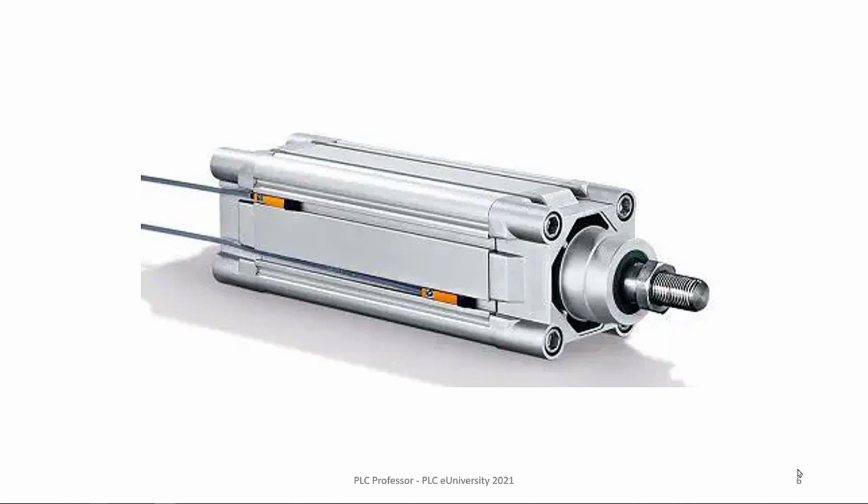Okay, so let's get back to this Hall effect. You've got electrons flowing through this conductor from left to right. If a magnetic field, even a stationary magnetic field, is moved in where the field has an influence over this conductor, then the magnetic field will encourage the electrons to go to one side or the other of the conductor.